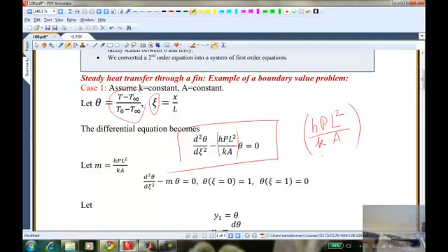Okay, so you can check this. You can plug in the numbers for the units for h and k and p. You will find that it is dimensionless. This is how dimensionless groups are born in some sense. In fluid mechanics, you will come across a lot of dimensionless groups: Reynolds number, Prandtl number, Schmidt number, things like that. These are all dimensionless groups that represent a ratio of two physically meaningful quantities.